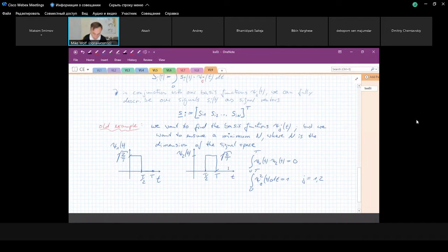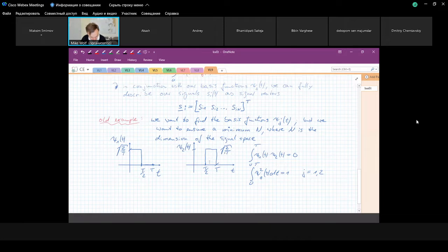By the way, if you take a look at the slides, I use different basis functions, but the basic properties between the signals, for instance, the signal energies or the so-called Euclidean distances, are independent of our chosen basis functions. We can use different basis functions, but physical laws do not depend on the coordinate system. For instance, if we rotate the coordinate system or if we shift it, the laws remain the same. And here it's the same. We can choose even other basis functions.